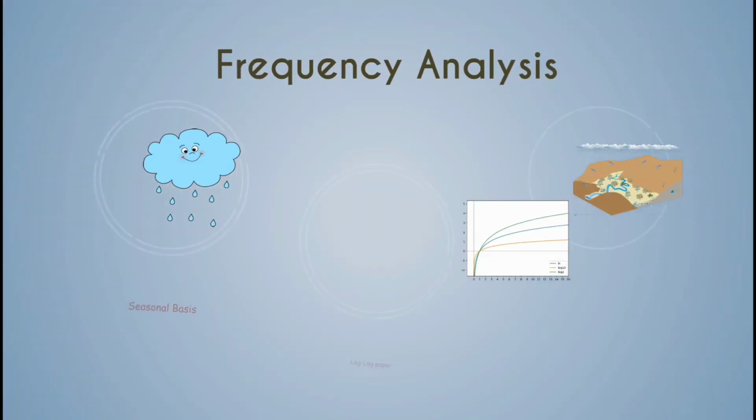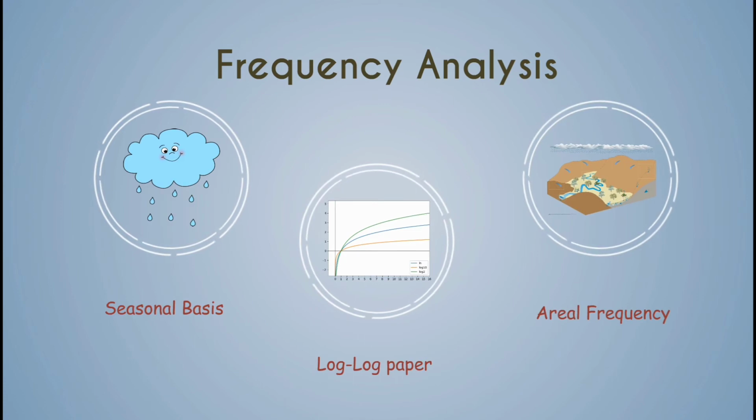Now, the frequency analysis concept is applied on a seasonal basis and for areal frequency. The rainfall records of deficient length have to be extended by the station-year method. The results of frequency analysis are plotted on logarithm by logarithm paper.